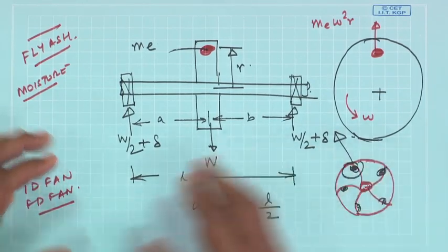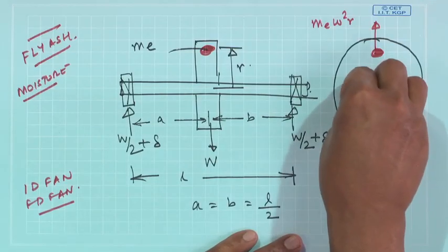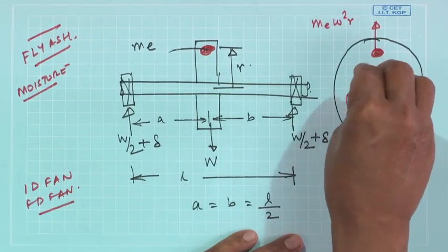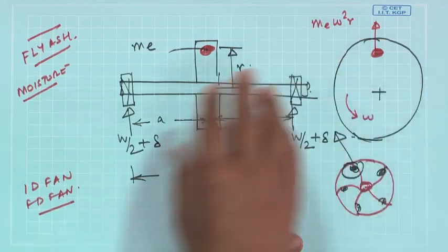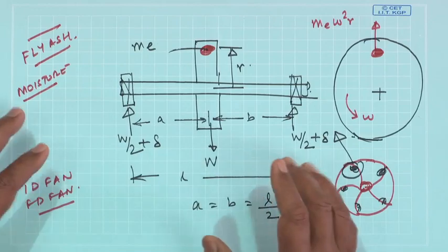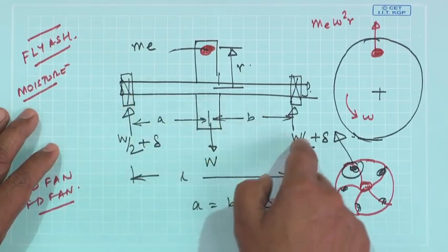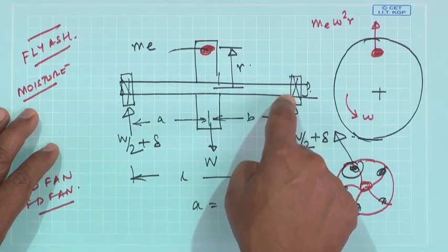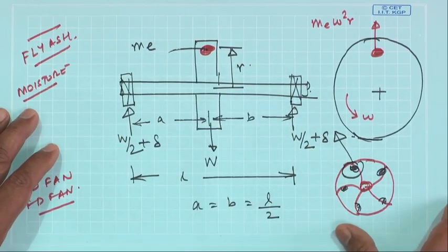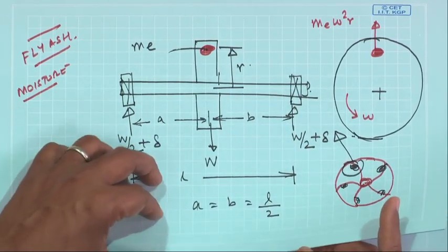And then of course, one leads to another in machinery condition monitoring. If an unbalance was let to grow undetected, this will lead to a bearing failure, and then you will be investigating a bearing failure without actually going into the failure because of this unbalance. So, these are some of the scenarios.